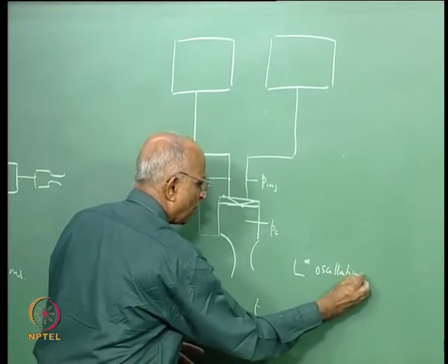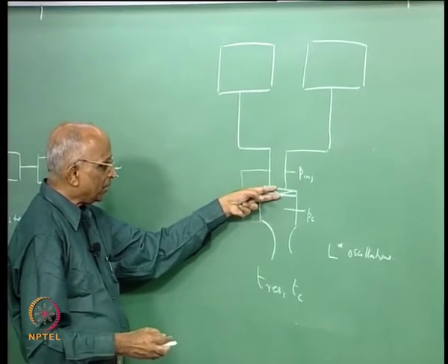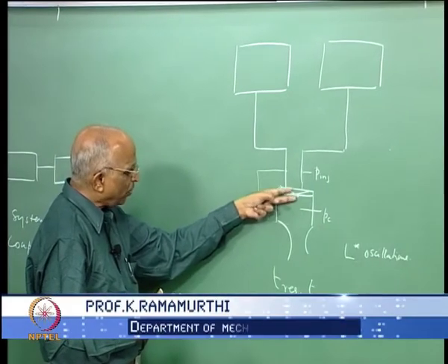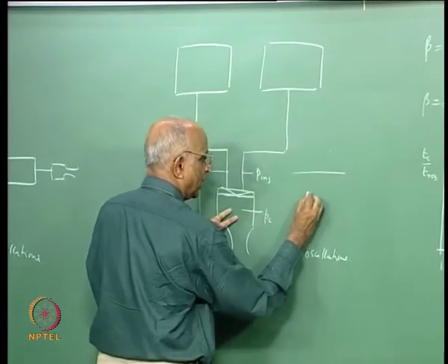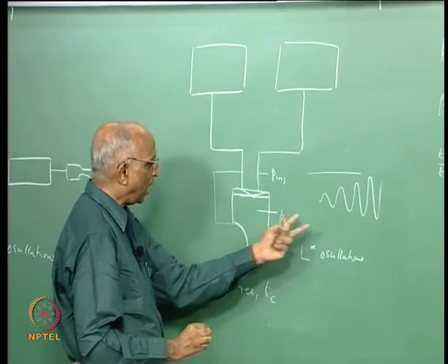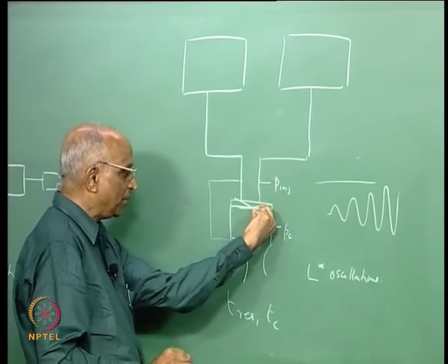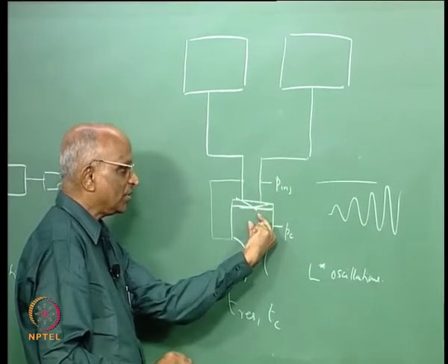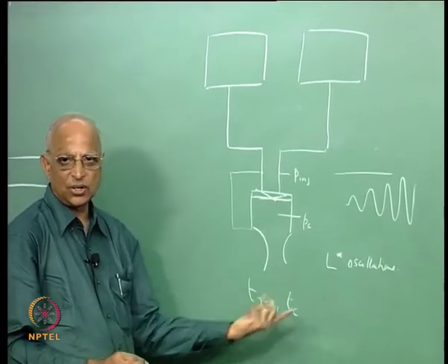In other words, all we have seen is that when the injector pressure drop is less than some threshold value, then instead of having a steady value of pressure, it is quite possible to get a diverging pressure. And these oscillations are linked to the feed system, because the feed is what gives you the pressure drop over here. If I have a very high pressure here, I will not get these oscillations, and therefore they are known as feed coupled oscillations or L star oscillations.